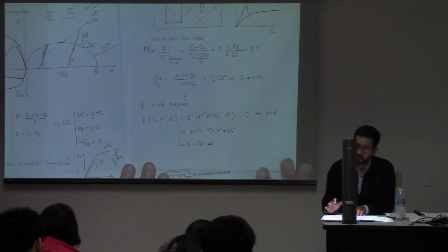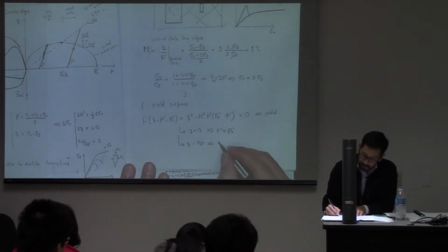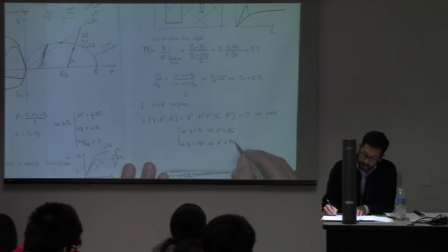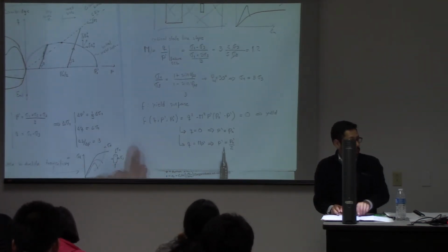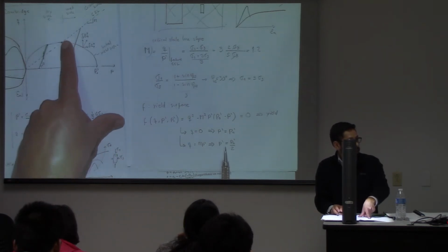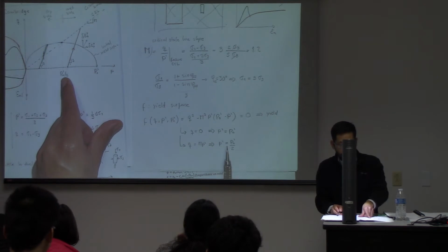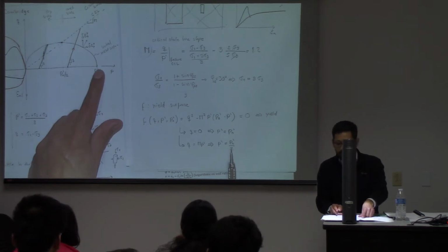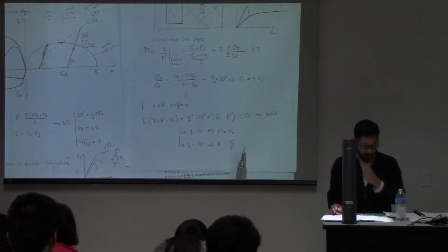You have to do some math, okay? It's not as simple as the one before, but it's not too difficult to solve. It's going to be 1/2. And that kind of makes sense, right? Because if you are at that point, your mean stress has to be half of the limit mean stress for the isotropic compression line.